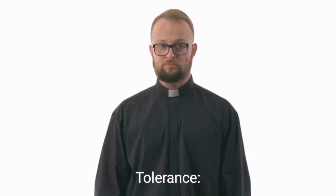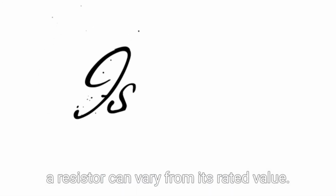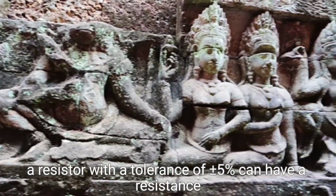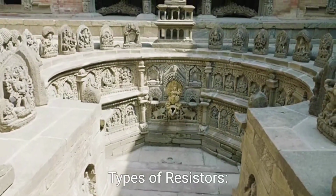Tolerance. This indicates how much the actual resistance of a resistor can vary from its rated value. For example, a resistor with a tolerance of ±5% can have a resistance value within 5% higher or lower than its nominal value. Types of resistors.